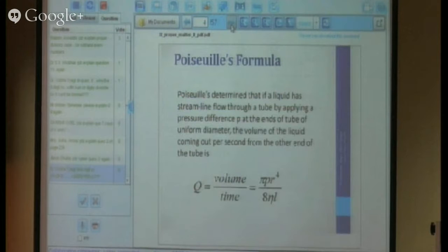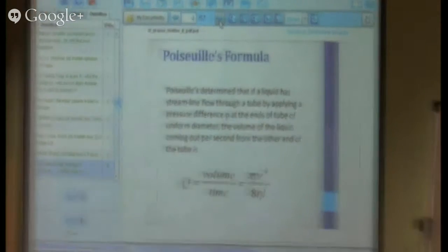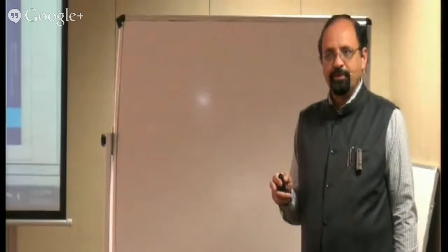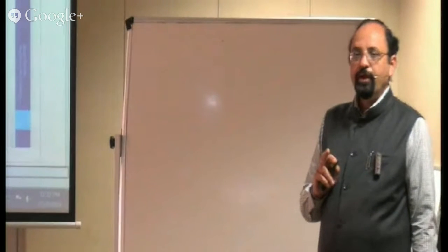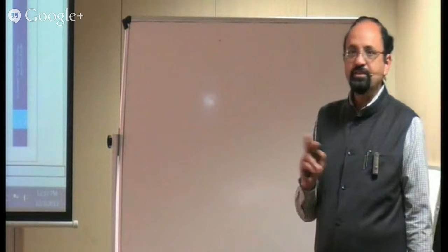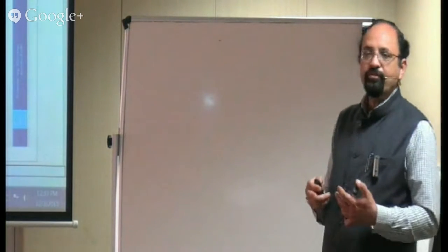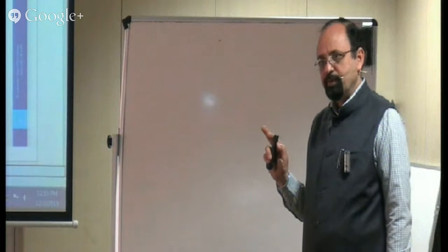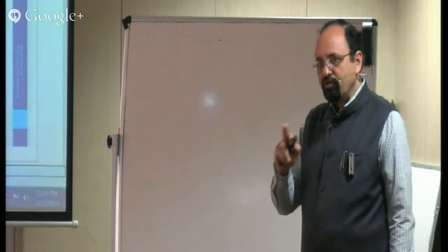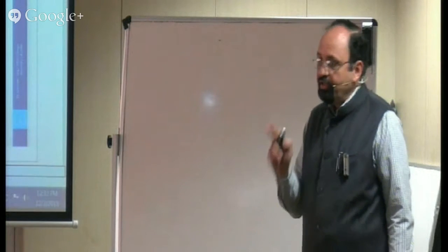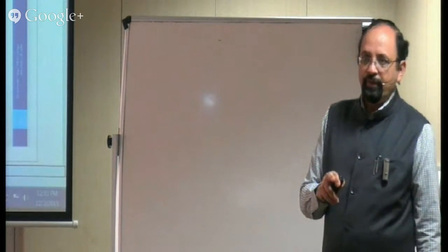See, in a previous lecture, I told you that you can use Bernoulli's theorem for the study of the flow of liquids. Bernoulli's theorem is basically the energy concept, but there is a condition. It is applicable only for those fluids which are ideal. That means there is no viscosity. What will happen if I have viscosity? One thing, I cannot use Bernoulli's theorem. But can I use the equation of continuity? Yes, we can use the equation of continuity even if the viscosity is there, right?